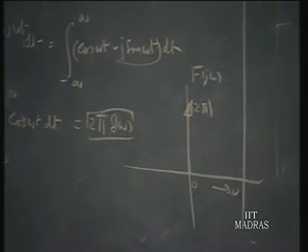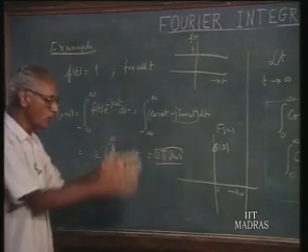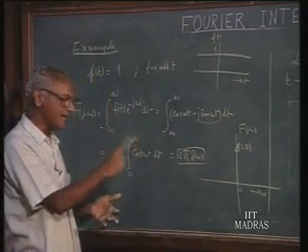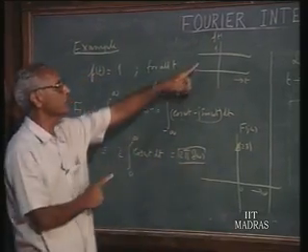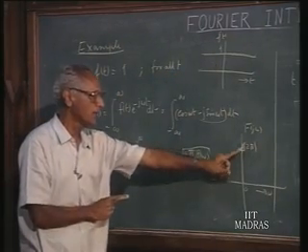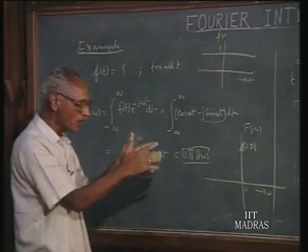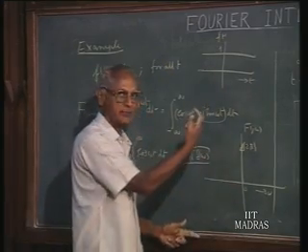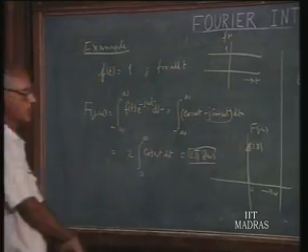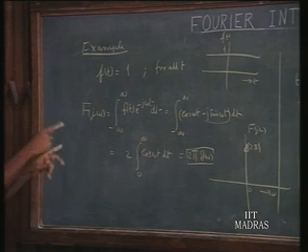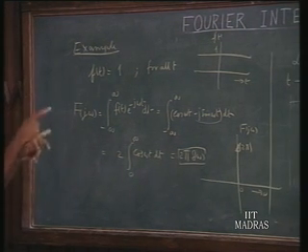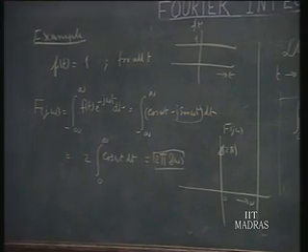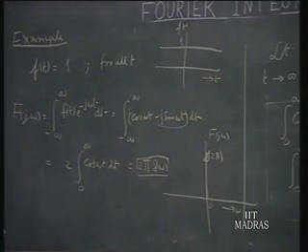This is a pure DC term. Therefore, you have only a DC component here and no other components, and at the DC we have a finite amplitude for the voltage. Therefore, you have an impulse function. Even though we are talking about coefficient density now, this coefficient density is infinite because there is a definite non-zero amplitude at DC. Therefore, the coefficient density is going to be infinite and it has a magnitude equal to 2 pi. We will develop this theme further when we talk about other periodic signals.